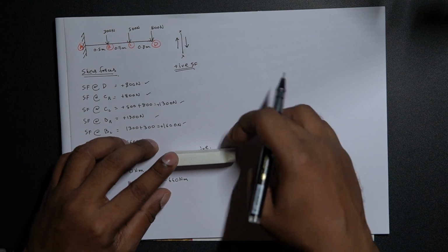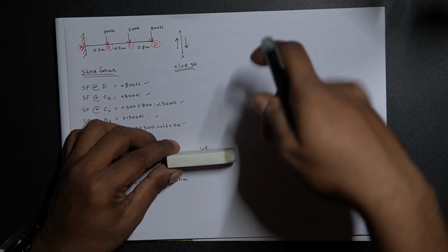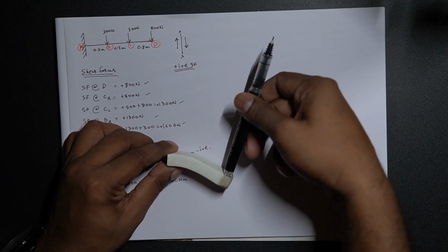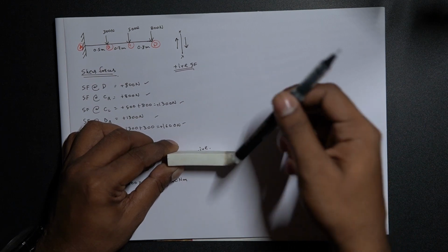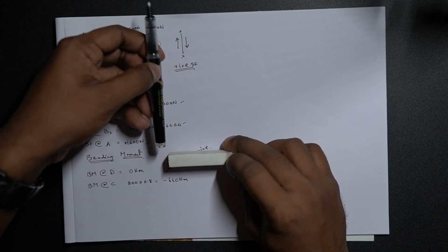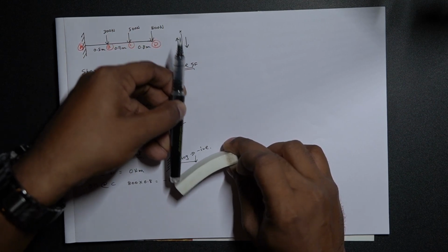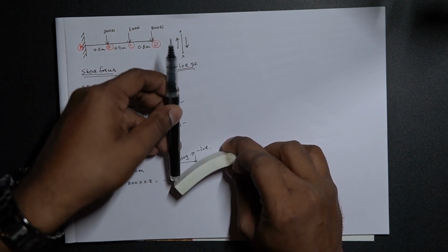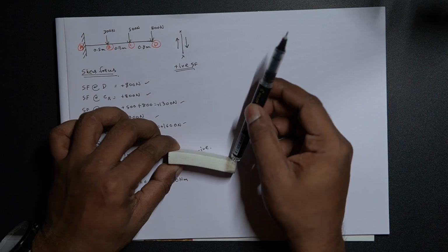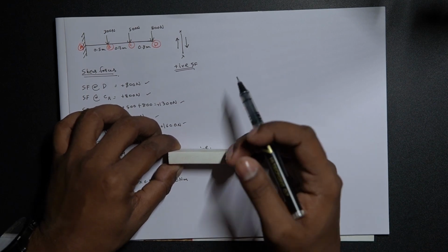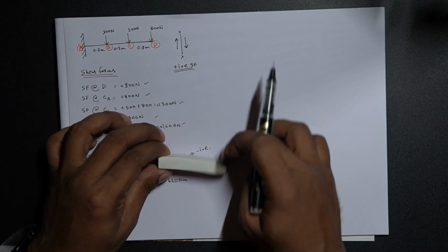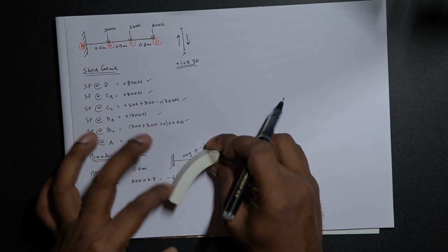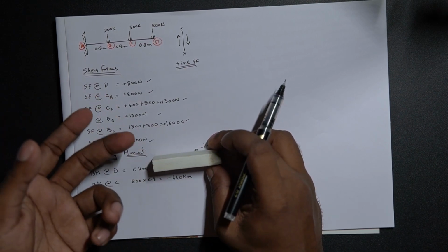For instance, in this particular case, when the load is acting over here, it is turning the beam in a clockwise fashion. And if the load is being applied over here with the fixed support on the right hand side, it is turning the beam in an anti-clockwise direction. If towards the left hand of the section is anti-clockwise and towards the right hand of the section is clockwise, we can consider that as a negative bending moment. Similarly, just like how the hogging is happening over here, clockwise movement, hogging action, we consider it negative. Anti-clockwise movement, though it is a hogging action, we consider it negative.